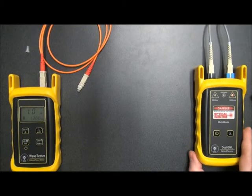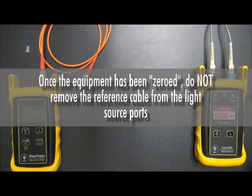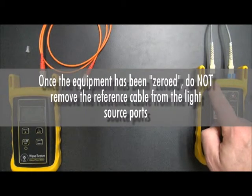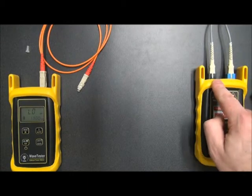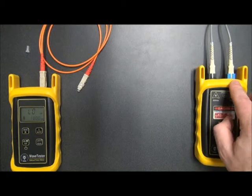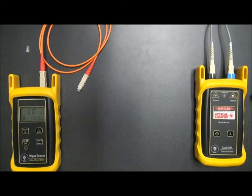Okay. Now, before we begin, I would like to cover a couple things that we need to really remember about reference cables, particularly with the light source here. The first thing is that you want to make sure that you do not disconnect the patch cables from your light source once the references have been set. If you happen to disconnect and reconnect, you're not assured of getting the same reference level again, and you will likely have to re-zero and retest.